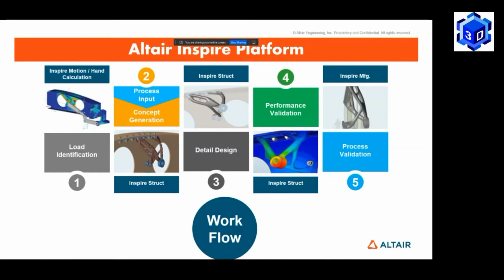Then you will actually go for printing. But before that, you do a virtual printing here, because printing itself is costly, and printing has its own print failure or build failure, which, especially for metal, is a very, very costly affair, right? So you have to make sure that everything will go as per plan during building, and after building, it will not see significant distortion. Instead of a human jaw, it might become a bow, and that might not fit at all. So all those things you will cross-check before you actually fire the print. And then if you are satisfied, you can fire the print.